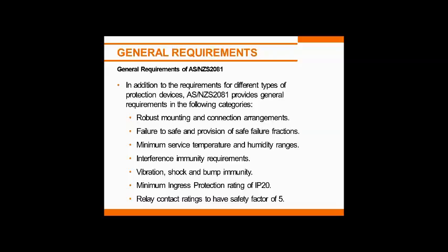The next requirement of the standard is that if the relay does fail, it fails to a safe position, so that the problem it causes is a safe one, not an unsafe problem. And to go with that, for the latest relays we produce, we have some sort of SIL information such as safe failure fractions or mean time between failures, something that a customer can use to work out his SIL ratings or the basic reliability of the system, or the relay he's putting into a system.